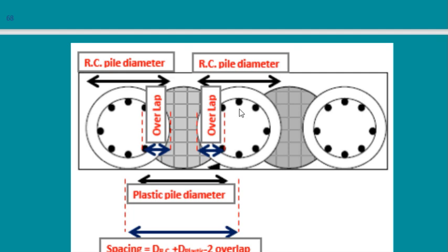So to reach higher depths, this needs some kind of lining of all the piles on one side, and later if I want to incorporate this as a permanent retaining wall, then, similar to the previous case, I will need to put cladding from this side to have a smooth wall instead of having bulbs of piles.